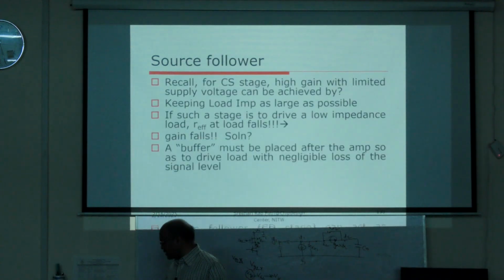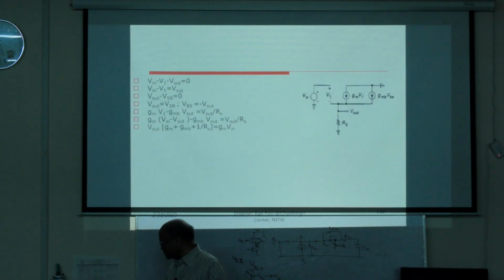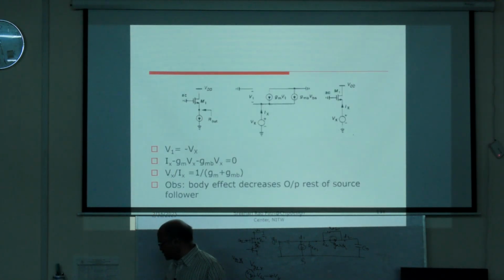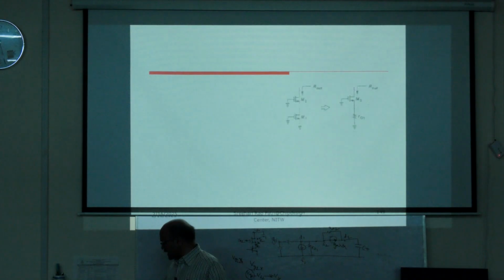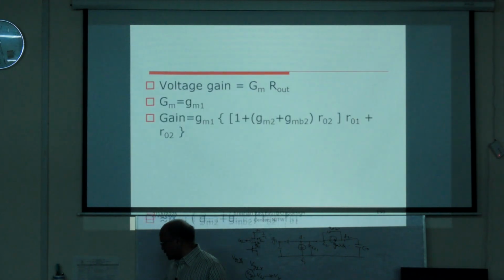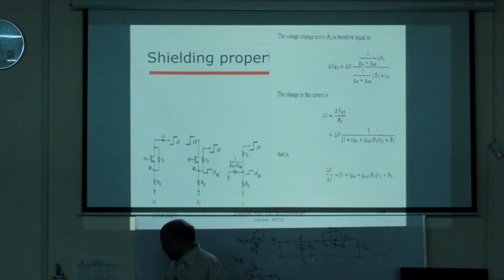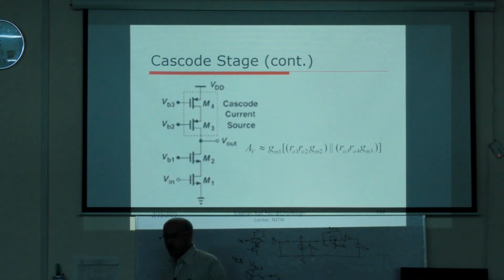And we will try to quickly move towards, we will not do all this. The cascode we have seen enough, probably will not deal much with that. Yeah, a cascode, I just would like to mention one thing, that the load of the cascode should always be another cascode. Otherwise, whatever you have improved the output impedance gets lost. If the cascode I have designed already, but you put one useless resistance over there, whose resistance value is less than the improved resistance, it comes in parallel with this, and therefore when two resistances are in parallel, then obviously the equivalent resistance is smaller than the smaller one, right?